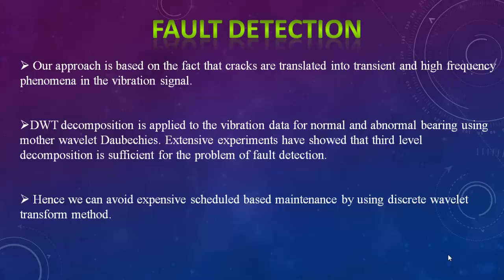Now, how we have seen fault detection, we can check it out. Our approach is based on the fact that cracks are translated into transients and high frequency phenomena in the vibration signal. DWT decomposition is applied to the vibration data for normal and abnormal bearings using the mother wavelet Daubechies. Extensive experiments have shown that the third level decomposition is sufficient for the problem of fault detection. Hence, we can avoid expensive schedule-based maintenance by using the DWT method.